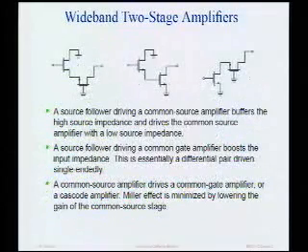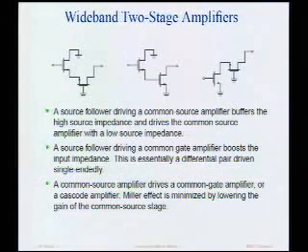Now, one way to fix these amplifiers is simply to go to 2 stages. And 2-stage amplifiers are very convenient, especially for integrated circuits, because transistors are really free. They're tiny. They take up very little area. So if you had to choose between a single-stage amplifier and a 2-stage amplifier, and area were a concern, it basically would not be a concern because transistors are so small in modern technologies. So we try to use more transistors to improve the performance of, let's say, amplifiers.